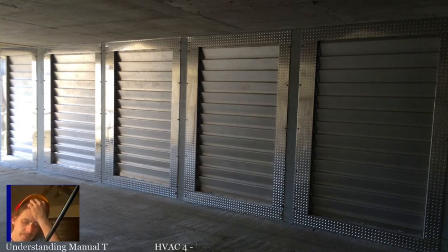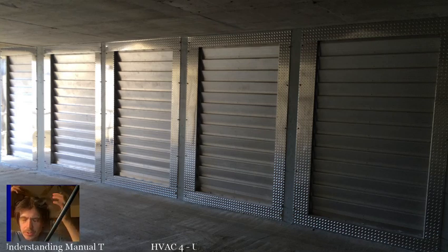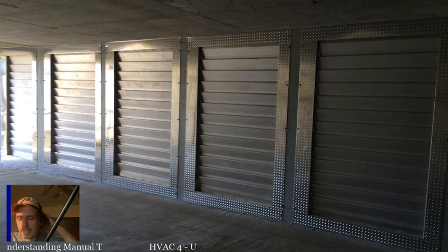Anytime you have non-vented equipment, just remember this. There are some small equipments. A lot of times it'll be listed as a decorative appliance, right? That's your most common non-vented equipment, something that gets labeled a decorative appliance. So it's a very low output fireplace or something like that. Or small room heaters sometimes are non-vented. Usually if it's under a certain number of BTUs, it might get approved to be non-vented.